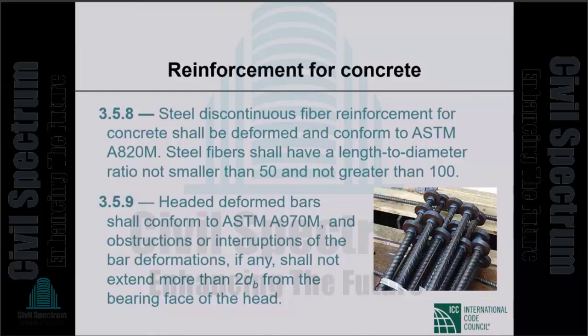Okay, this is recognized in ACI 318 as shear reinforcement under very tight controls. So this is an increasingly important item, in my opinion, that you should be aware of, the steel discontinuous fiber reinforcement. Other types of fibers like carbon fibers are not recognized by 318.